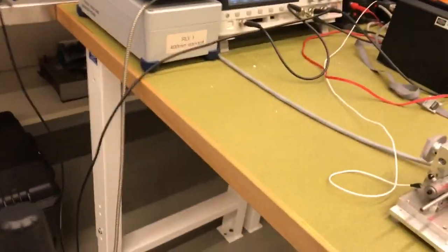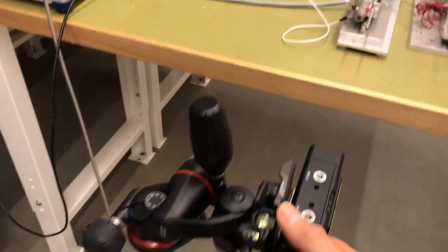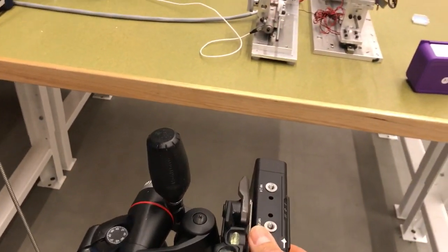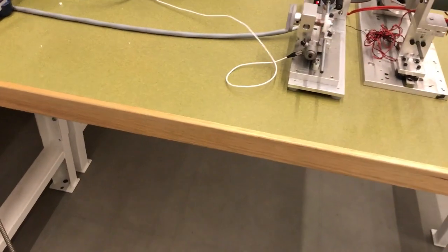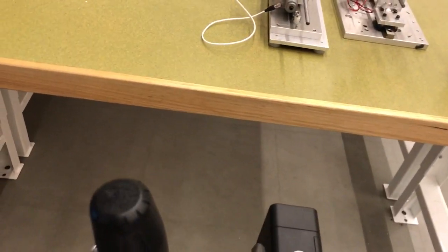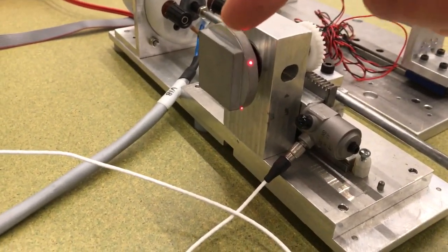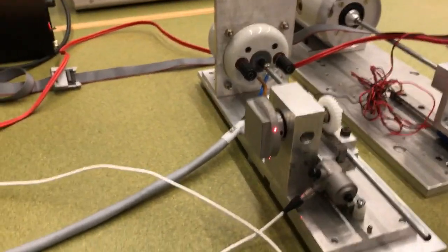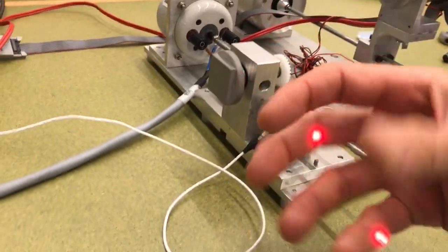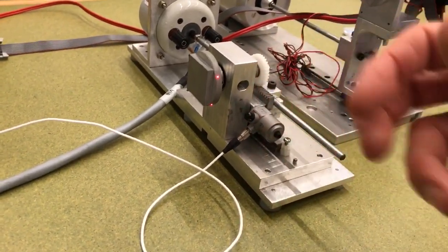In terms of the laser vibrometer, I will adjust this to 2 output laser beams. I am going to focus those 2 beams on this angular wheel which is rotating. I have a circular cross section here and a square cross section alongside that. This is the measurement that I'm making of angular vibration, of just the rotation of the wheel.